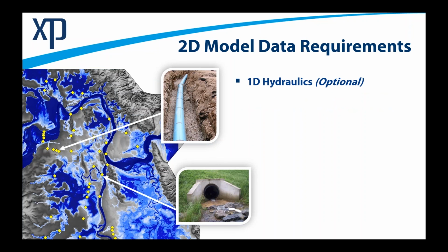If, for example, we're dealing with a conveyance area which has 1,000 cubic feet per second or 1,000 cubic meters per second, modelling a culvert as part of the floodplain that was, say, 30 centimetres in diameter really isn't going to have any significant impact on the hydraulics, so you wouldn't bother putting that in. At the other end of the scale, if there's a bridge that has an opening which is 5, 10 metres wide, then you should definitely be including that in the model.